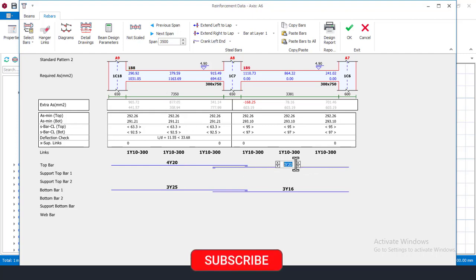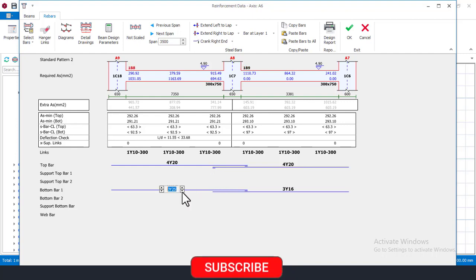Because of the length of the beam, that's why I make here to be 4Y16, and then increase to 4 numbers. Okay, it's failing, Y20 is okay for that. I'll come here, everything now looks okay, we don't need support bar for this right now. Come here and give this Y20 and increase to 4. That's okay. And then come here. Okay, that's fine. So we can have this perfectly.